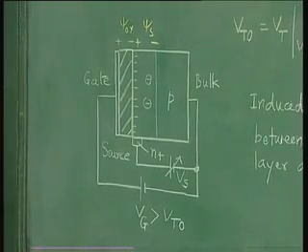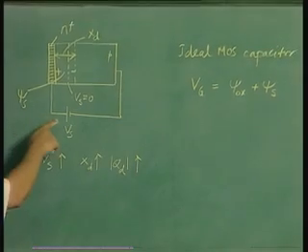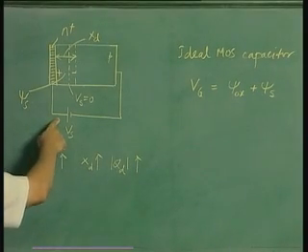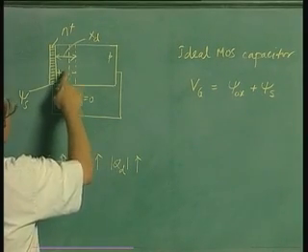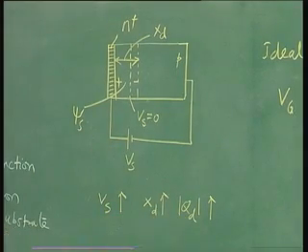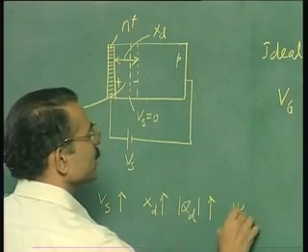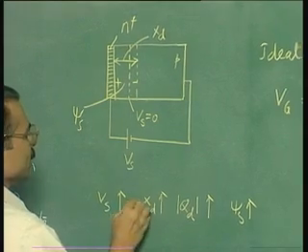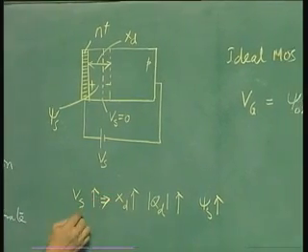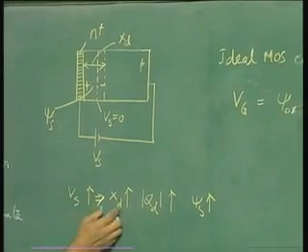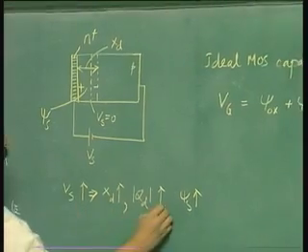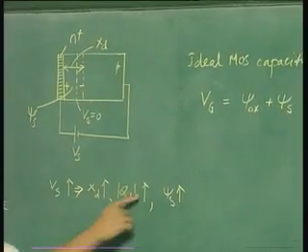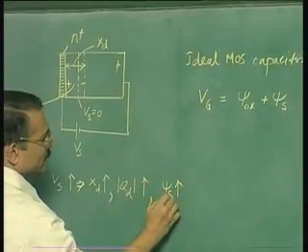So clearly now what this diagram shows is that as Vs increases, your XD is increasing, the depletion charge is increasing, and so psi s is also increasing. So Vs increasing implies the result of Vs increase is XD increasing, magnitude of QD increasing, and psi s also increasing.